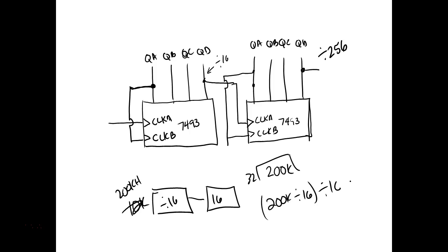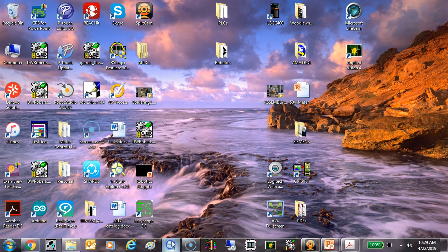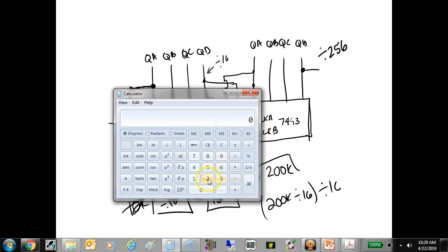So what would be my output frequency? This is 200K, 200K divided by 256, so it'd be 781.25 hertz.